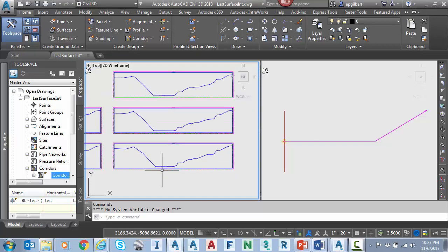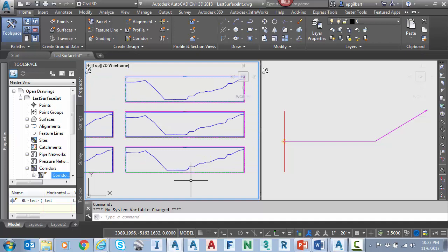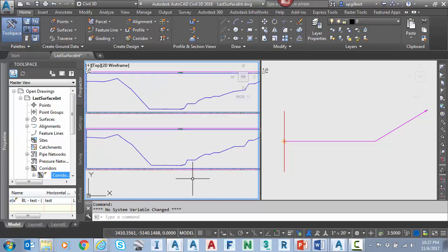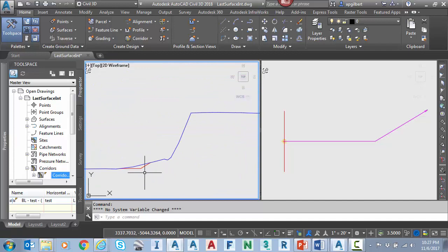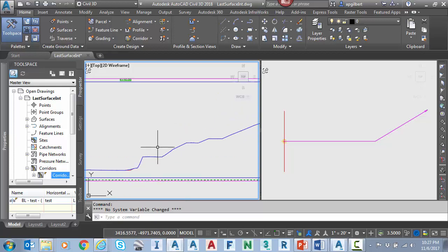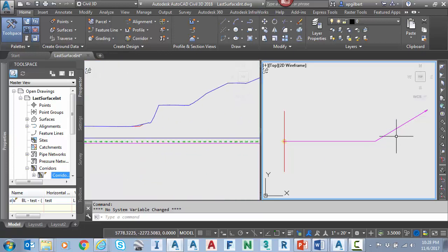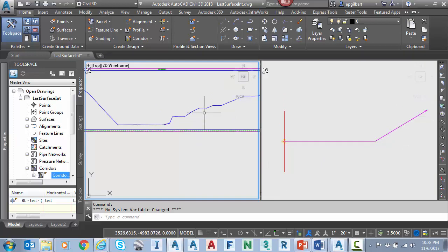So in an example similar to what you see on the screen on the left side, this could represent an earthen channel, a riverbed. In this case, it's actually a mine, like a limestone mine. But the result would be basically, I would like to follow a slope. You can see I have an example here where I'm just doing a simple generic link to slope to surface. But I would like to find on that slope path the last intersection point. So in this particular slope, you could see it would probably be right in here if I could do that. And of course, the slope to surface standard generic link is not going to work.